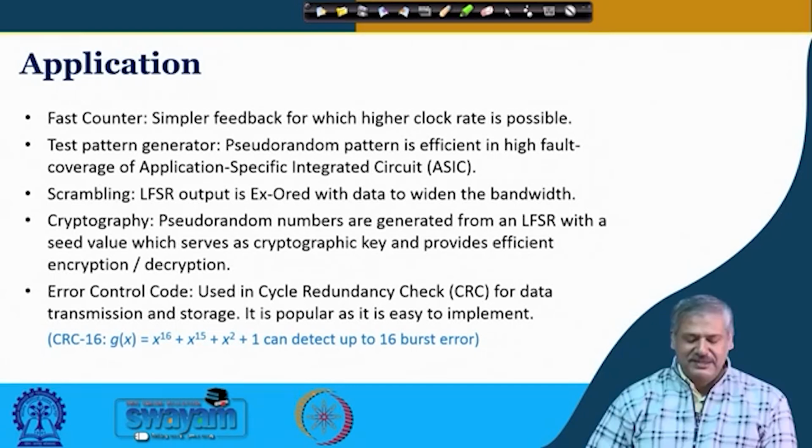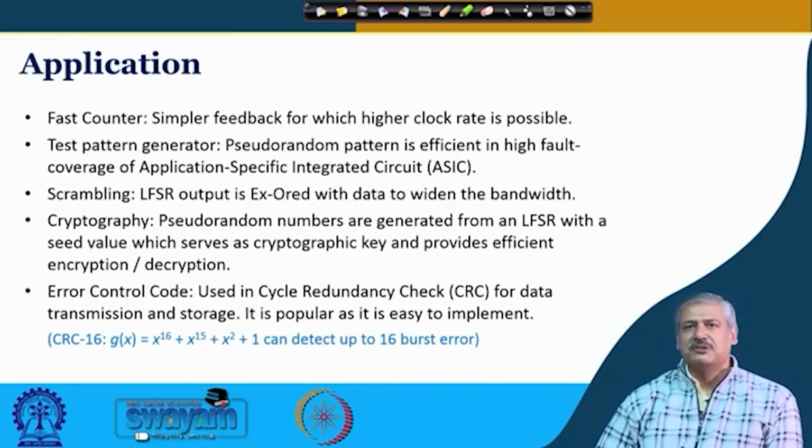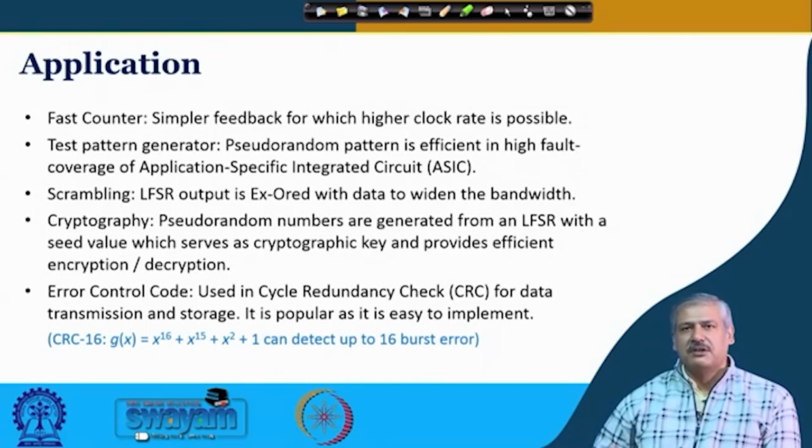There are many applications of LFSR. Here I have listed a few, and the majority of them come from its ability to generate pseudo random sequences. If the counter does not require states to be sequential increments like 0 0 0 1 0 0 1 0, any kind of states can be there, and then a fast counter can be made of sufficiently long length, up to 2 to the power n minus 1.